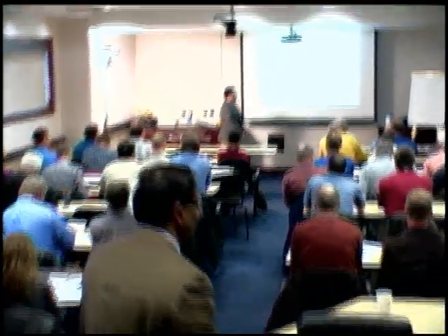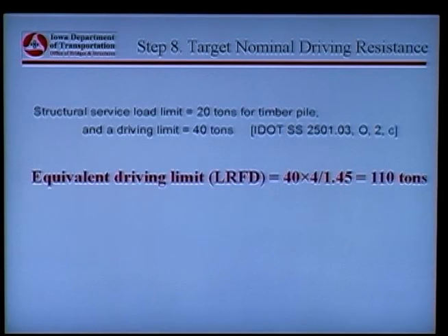All right. For especially timber piles, we want to limit the driving energy applied on the timber pile, to prevent the timber pile from damage. So in the interim bridge design specification, there's a criterion of a service load limit for timber pile of 20 tons and a driving limit of 40 tons. Okay? And this 40 tons in the ASD or interim procedure has an embedded factor of safety of 4 in it.